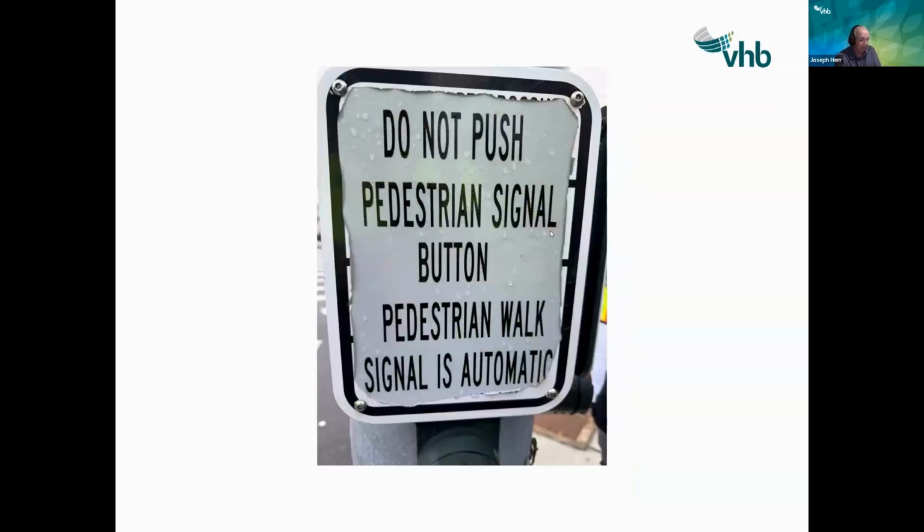The signs are a little different, going around, some interesting signs out there. This sign was actually put in Providence, Rhode Island during COVID. They didn't want folks to go and push the button. So what they did is they put the phases on PED recall in the controller, and they put this over the sign. They didn't do any wiring. They didn't disconnect the wiring.